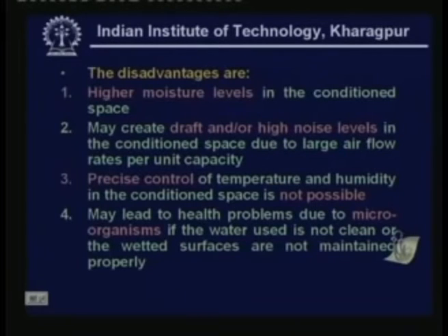And the fourth disadvantage is that these systems may lead to health problems due to microorganisms if the water used is not clean or the wetted surfaces are not maintained properly. If you use dirty water or if you don't clean the evaporative coolers from time to time, then fungus or algae may form inside the evaporative cooler or on the wetted surfaces, which may give rise to growth of microorganisms. And since air blows over it and you inhale that air, this may give rise to health hazards. So you have to maintain it properly so that no fungus or microorganism formation takes place.